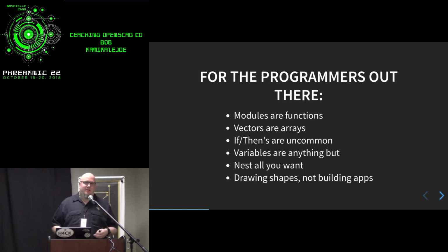Modules or functions. Terminology change. Instead of creating a bunch of functions that do stuff and output results, you call them modules. That's not to be confused with the fact that there are also actual functions still in OpenSCAD. The difference is anything you do in a module has the immediate side effect of generating a 3D object, whereas functions are kind of like the math kind. They're strictly functional and that's it.